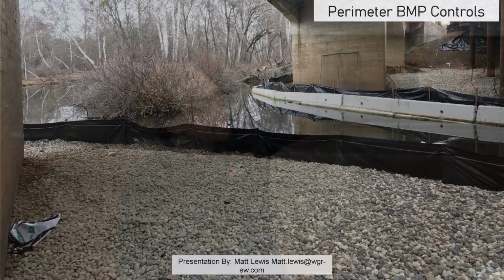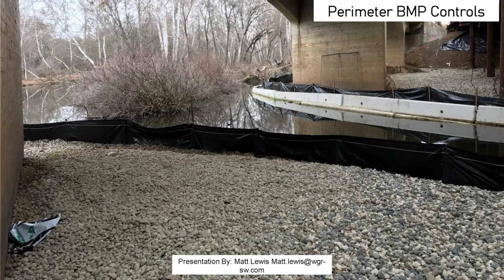Usually what they never do is the added twist. So that's up to you as inspectors if you want to call them out for that. Technically, that's what it's supposed to do. I almost never see them do that, almost never. But if you can see the stakes on the opposite side, it's obvious proof that they haven't twisted the silt fence around it before they staked it. So just FYI.